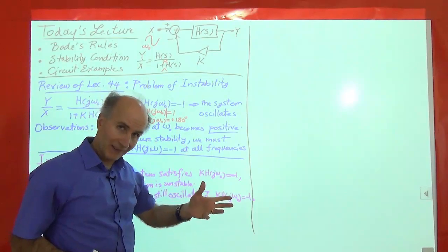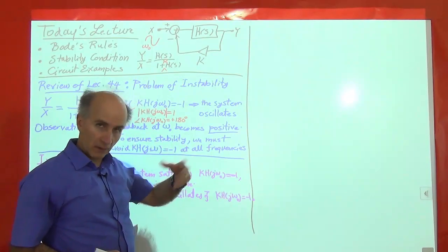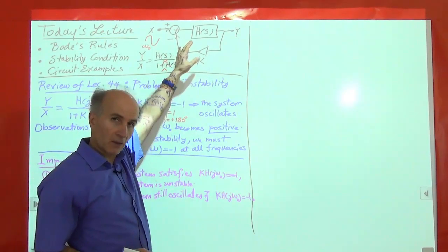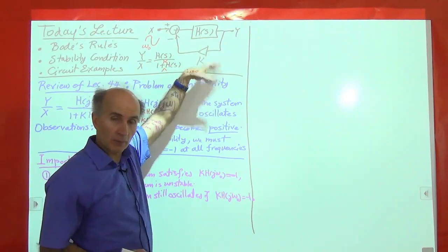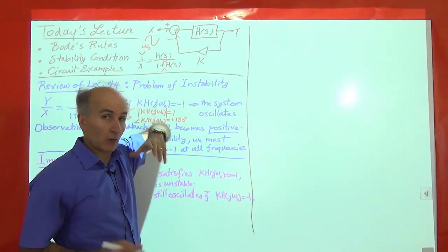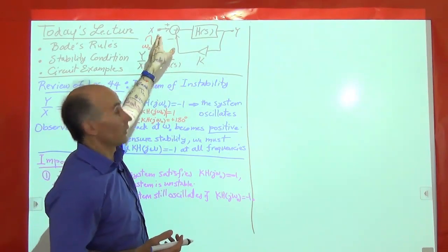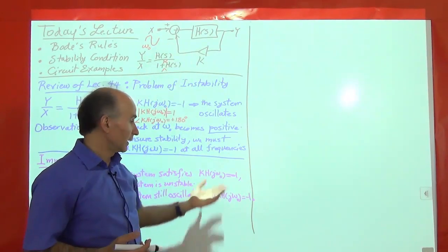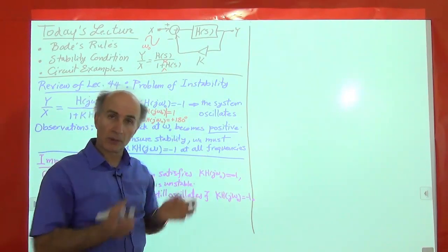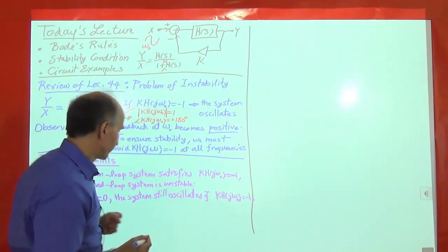I won't go through the details exactly here, but there's always some noise or some other conditions inside here that will make the system oscillate. All right? So in other words, if you're trying to build an oscillator, we don't have to have an input for it, right? You can just build this loop, guarantee this condition, it will just burst into oscillation.